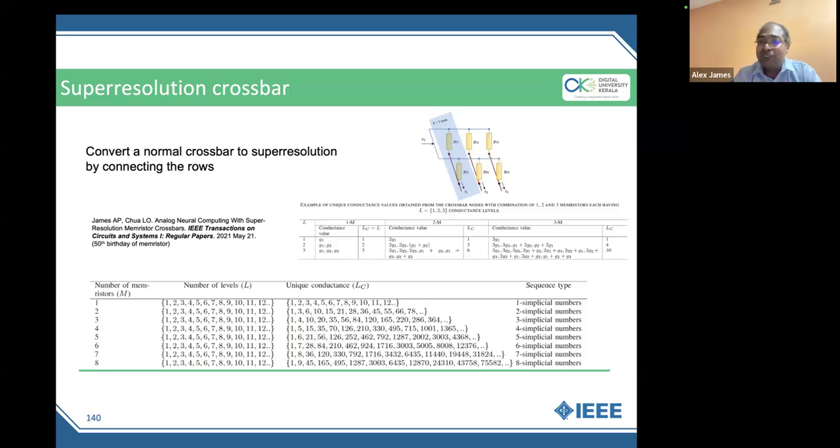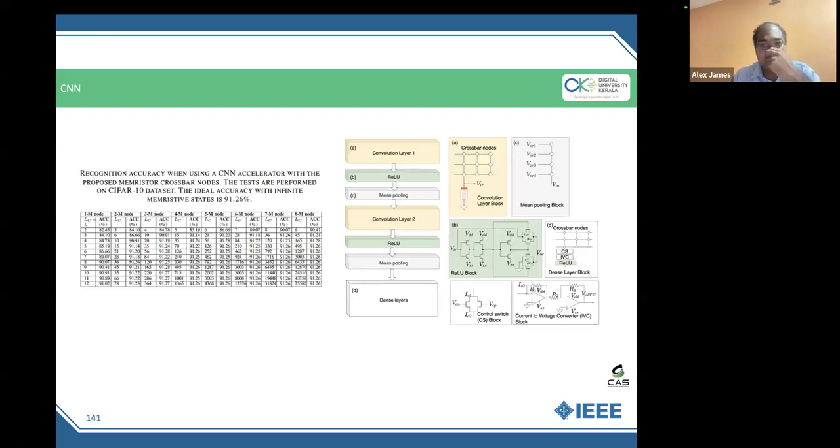designing something that reduces the number of conductance levels and things like this, which also means that if the conductance variability, the resistance values, are changing, that is also taken into account. So that way, it tends to be a bit more robust. This was the convolutional neural network. And with as few as something like 7 memristors in parallel, it could give a few number of levels, 3 levels or 4 levels, and you could still get the same software-level performance, same number of epochs, everything.